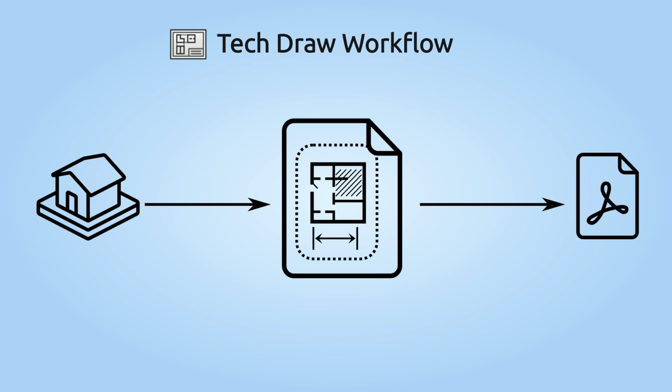The disadvantage is the current limitations of the TechDraw workbench. It is not possible to achieve all the needed graphical outputs at this point. TechDraw workbench was developed mainly with mechanical engineering applications in mind, so there is currently very little AEC-specific functionality available. At this stage, it is possible to create only simple study stage documentation using this workflow. As FreeCAD development moves fast, I think it will be possible to create more advanced AEC drawings using this workflow in the future.